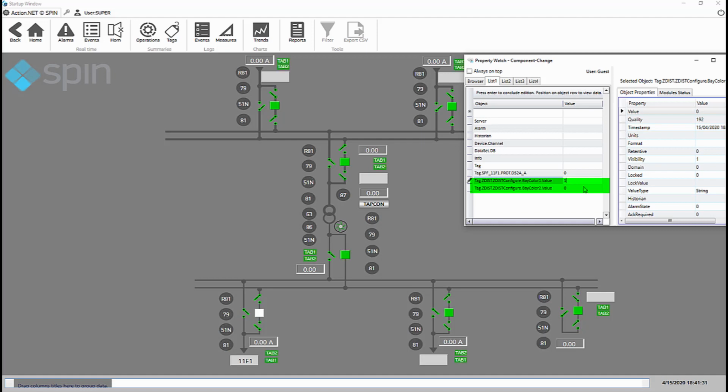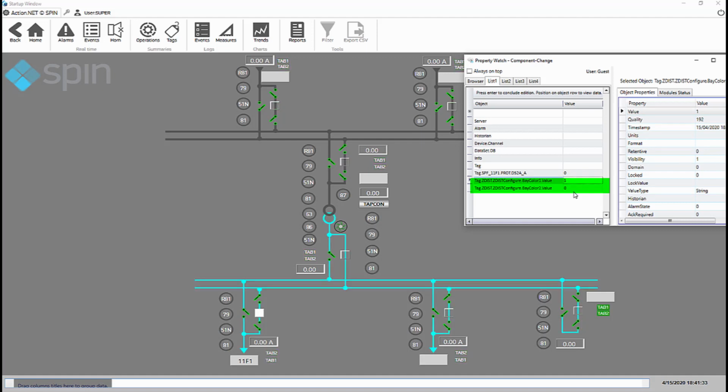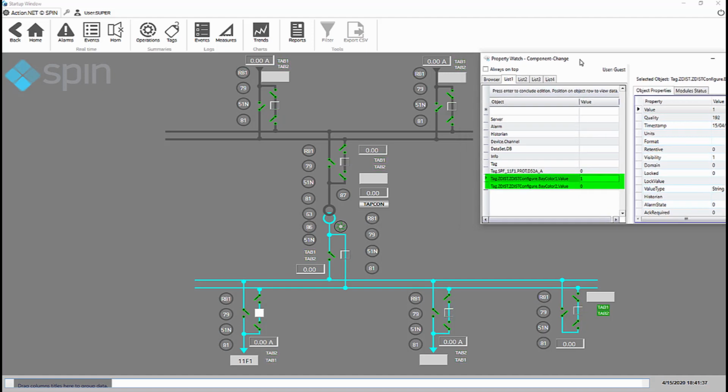And the colors associated with its comment attribute are moved to the color of the lines of all voltage level elements. If we wanted to change the colors of the voltage level, just change the attributed comment of the bay color 1 and 2. If, in the single line diagram, there are 3 voltage levels, a new tag, called bay color 3, must be created, and the respective bay symbol must be included in the symbol library.